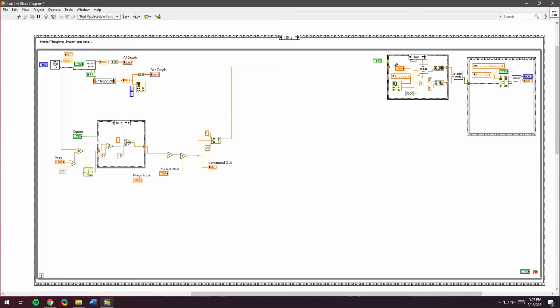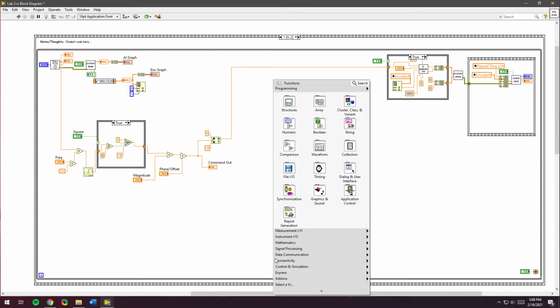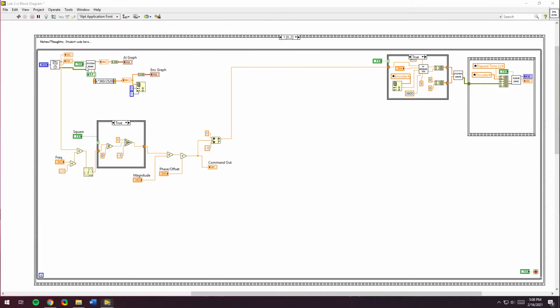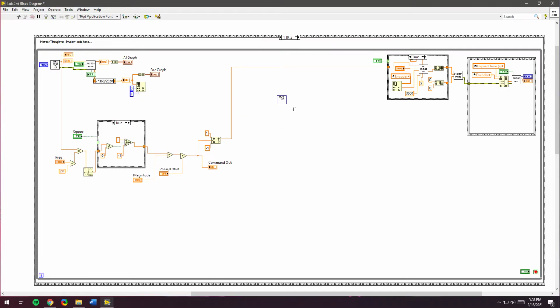You can see, like I said, we're not doing closed loop control anymore, so what we tell the motor to do never looks up here at what our actual flywheel is doing. But we are still interested in what that flywheel is doing, so we're going to do some things with that now. We're primarily interested in the velocity of the flywheel, since that's what our transfer function is going to be in. So to get that velocity from position, we're going to use a math tool higher order. I just right clicked, selected a VI, and then in the class library, if you go to tools, it's right here, math tool higher order.